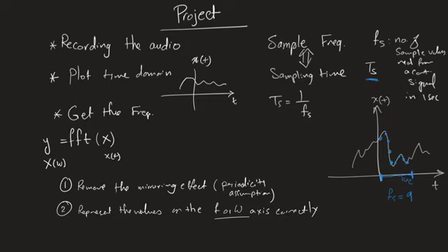So if for any reason the frequency domain signal is continuous, MATLAB will not be able to deal with it. So there are two things that happen when you are using the FFT. There is an inherent assumption that your input signal is periodic, even though it's aperiodic. So whenever you give it a signal, for example, 1000 values, it assumes that they repeat again and again and again. And not only that, it also assumes that the output coming from here is going to be a certain number of values, and then those values repeat again and again and again.